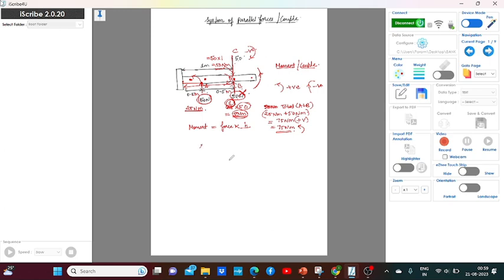The resultant couple will be couple by A plus B plus couple by C. Couple by A plus B is 75 Newton meter, and it was positive because it was anti-clockwise, and couple by C is negative because it is clockwise, so it is 50. So the resultant couple is 25 Newton meter. By this 25 Newton meter, the door will open on this particular side.